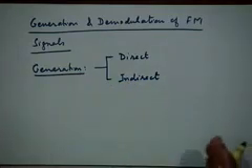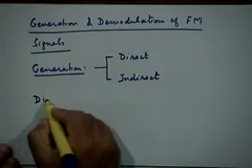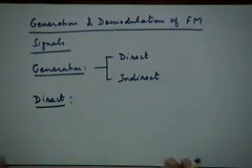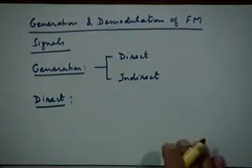The direct method actually uses a device. What do we want? How can we generate an FM signal? Just think about it. How do we generate a sinusoidal carrier? What do we need for that? An oscillator of suitable frequency, right? Now what do we want? We want the frequency of this oscillator to depend on the amplitude of another signal, right?